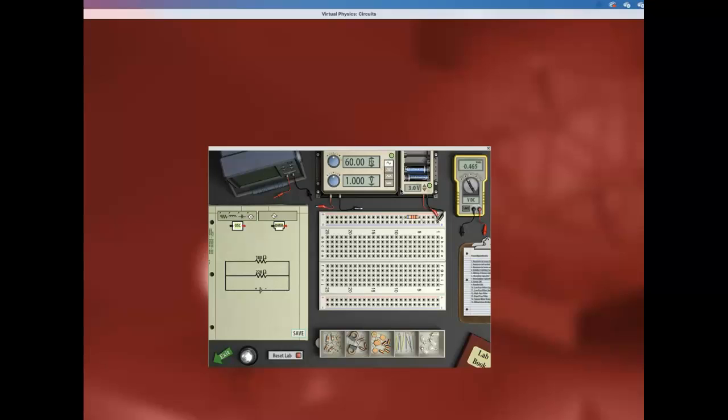You will now make several current measurements on that circuit. Record all the measurements. Watch the lab video for this. We must make some adjustments to the circuits below by adding a 1 ohm resistor in series with the power supply due to the software. Okay, now we are going to do that. Then I will add another resistor when I want to measure the current across. I will show you, but just for now,